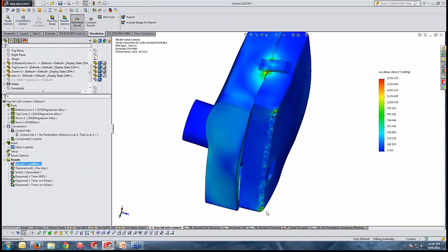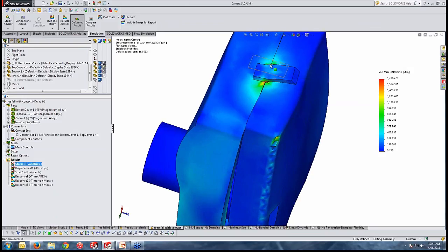Also, as we expect, we have the stress singularities on the impact, that is expected, but since these two components can be separated, we see the stress. That is considerable information to consider for designing this, let's say, snap-through assembly feature.